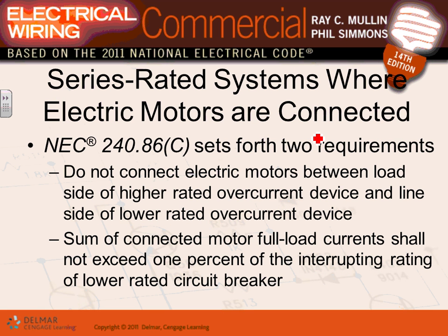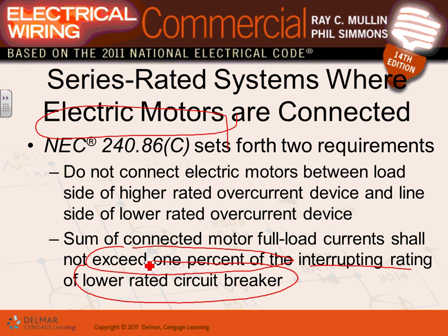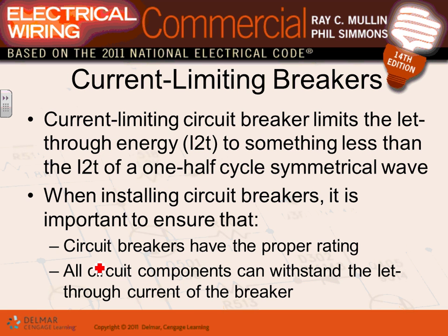Series rated for motors. When you have motors in a series rated panel, guys, you have to make sure that you don't exceed 1% motor load in the panel that's series rated. The sum of connected motor full load current shall not exceed 1% of the interrupting rating of the lower circuit breaker. Otherwise, you cannot do series rating. And I know series rating is an engineering matter, guys, so probably we'll deal with that.